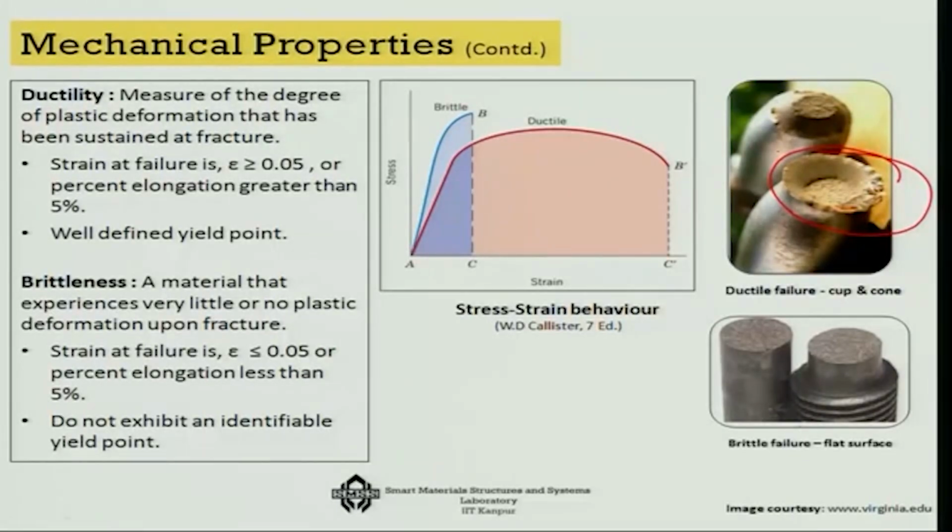So, the difference between a brittle and a ductile system, for which I have already drawn the stress strain curve, is precisely the presence of this plastic strain for a ductile material, and it is absent for a brittle material. So, that is a very important point that we have to keep in mind while comparing various material properties.